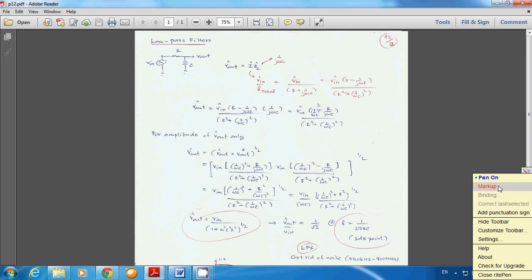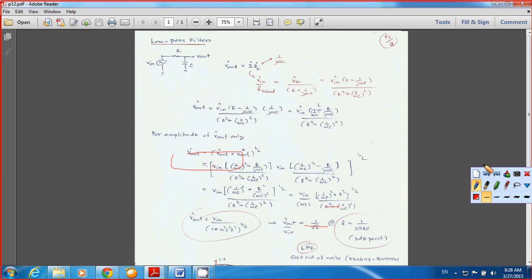Okay, next one is the low pass filter. If you understand how the high pass filter works and how to design it, you do the same thing for the low pass filter. That should not be so difficult here. As I told you before, for the low pass filter, you want only the lower frequency signal to pass to your output, and you don't want the high frequency signal to show up at your output. So you want your frequency response to be like this one.